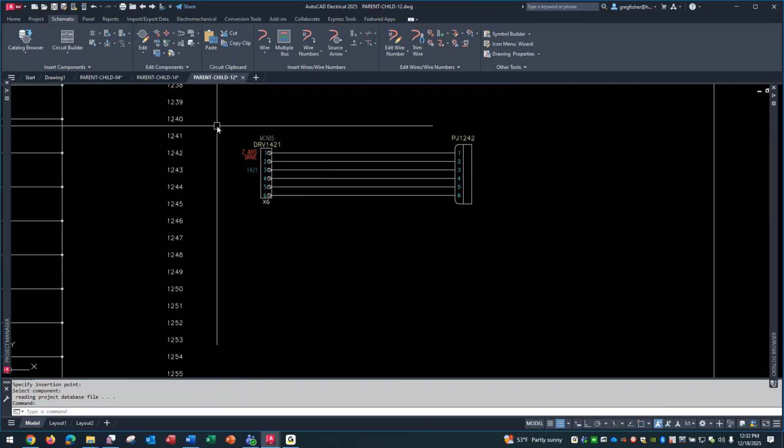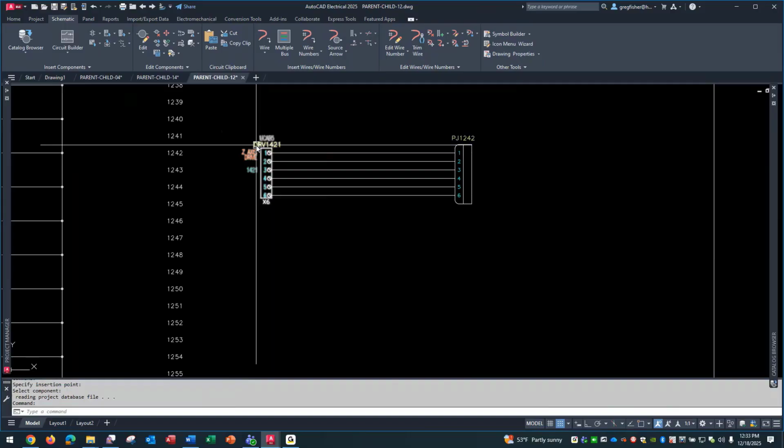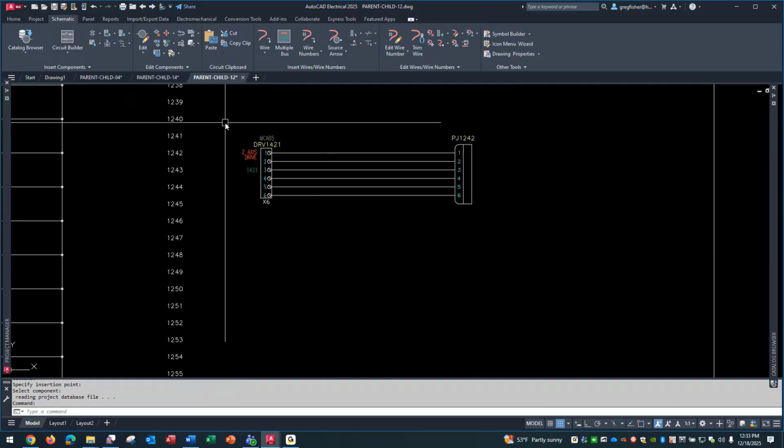You just saw that in the catalog number under the pin list column. It was undefined because it's not the contact. And then you just fill in the terminal/pin numbers to go to whatever symbol that you want. So that's my whole point here: parent-child relationships are not just about relay coils and contacts.